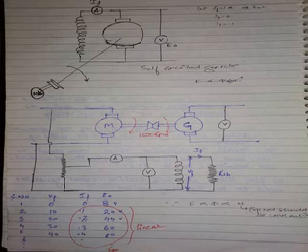When you apply some voltage across the resistance, what happens? Automatically the current will increase. If you plot a curve between V and I, what will you get? A straight line passing through origin. So the slope of that will give you the resistance value. So this is field winding resistance RSH. So what is VF by IF? RSH, the original resistance of the field winding.